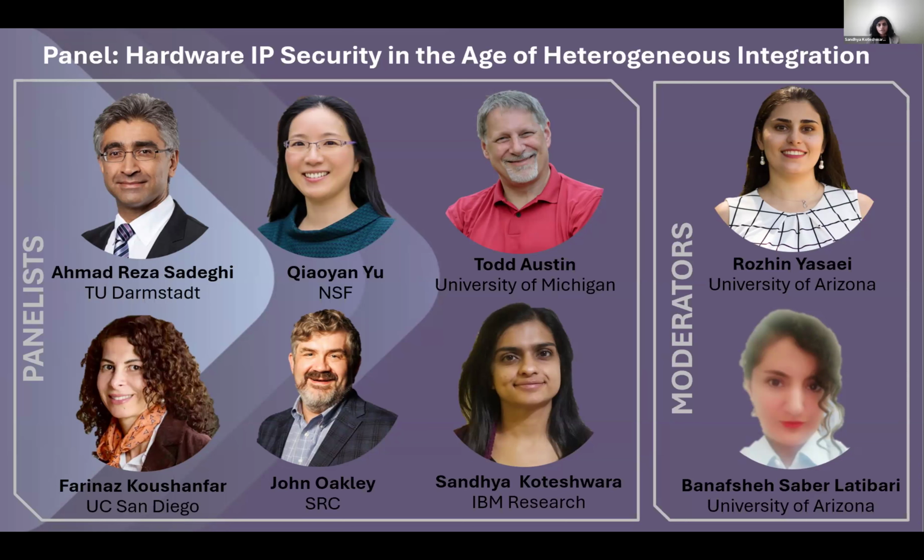So I do work in the CI consortium. I'm in the security and manageability work stream. That's our primary goal, to make sure that we have security included from the very beginning, right? As the management spec is being drafted, we are adding in provisions for security. This includes very early things like how do you load firmware into a SIP? You have provisions where you can verify that firmware. You have provisions where the root of trust can verify the authenticity, for example, of the chiplets before it sends the firmware to that chiplet.